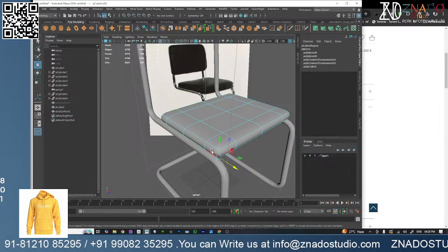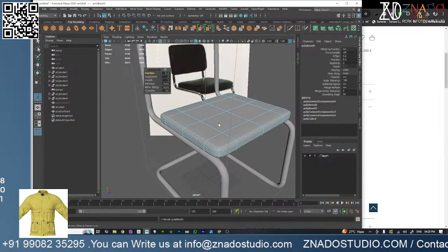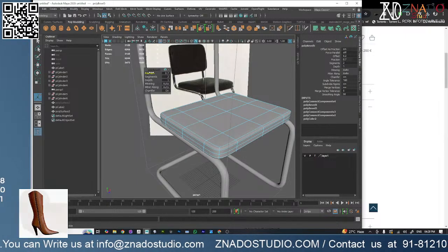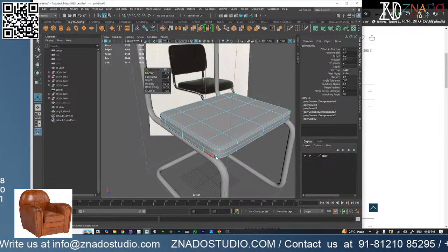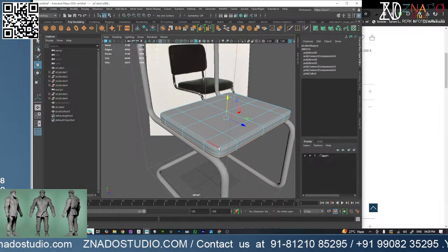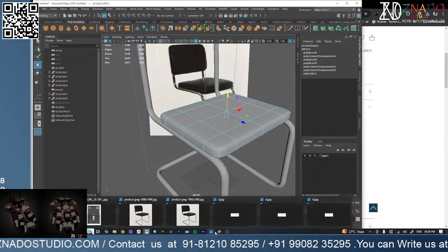So what I'll do here in the middle is add one segment. It is connect, add a bevel on top, okay. Increase the fraction. So it is almost there. This part, I'll push it up just a bit. Done. This one, I'll put it down just a bit. Done.